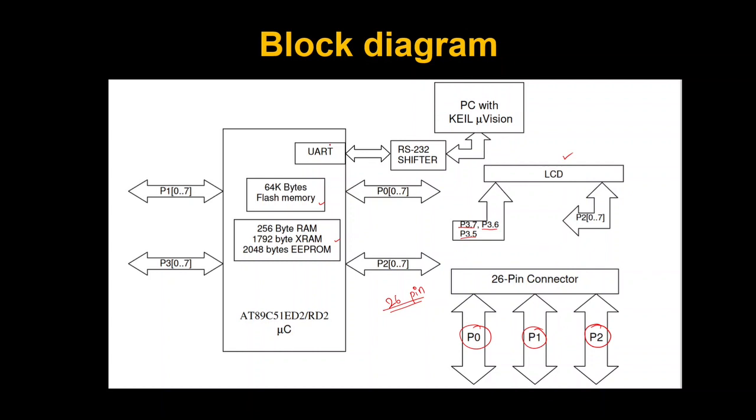Here is the UART communication, which is serial communication. It is interfaced through RS-232 to your PC, so it communicates with your PC and Keil. We saw a problem while discussing theory: what is the problem with the TTL logic from the 8051, and what is the problem in communicating with your PC using this TTL logic? To eliminate that, we have a few ICs, so that we can eliminate those problems when communicating from the UART serial protocol to the RS-232 protocol.